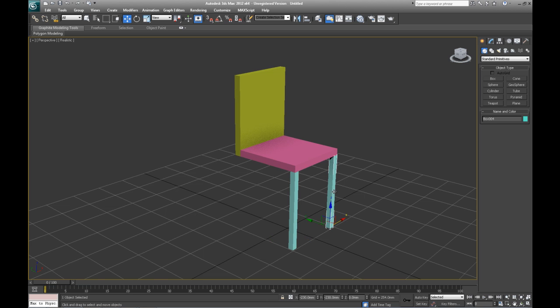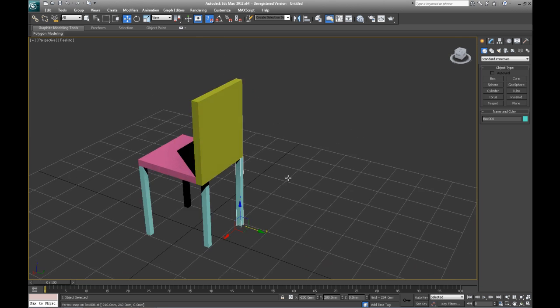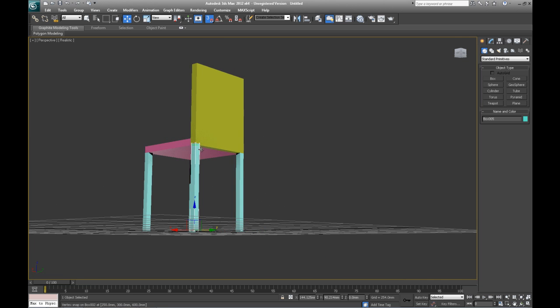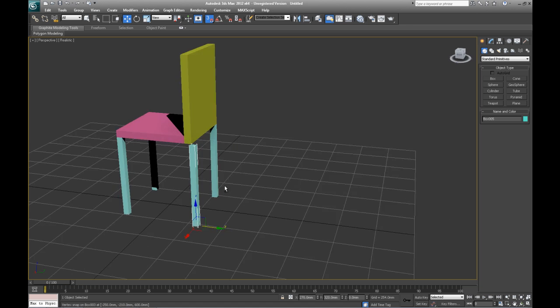What we're going to do is duplicate these two here. So I'm control selecting both of them, holding down shift and pulling out the legs there. I could use the snapping tool again now if I wish to, so I could have those two there. I'm going to create an instance and I can turn on the snapping tool, and I could then snap this object to, oh that's the wrong vertex actually, this top corner here, now let me get a proper grip on it, to the top corner there, and from here I could snap that corner there to that corner there.